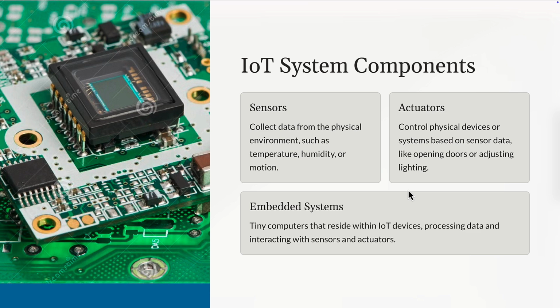So the lesson learned, now we need to have low power devices. There are different types of networking protocols. Communication is the big bottleneck in terms of energy consumption, and this is why when we have battery powered devices, usually we will use the ZigBee protocol. This is at the network layer, and in the MAC layer it's called IEEE 802.15.4 and some of its variants, like IEEE 802.11 that you studied on Wi-Fi. Did you study networking? Yes. Okay, so you understand these terminologies, right?